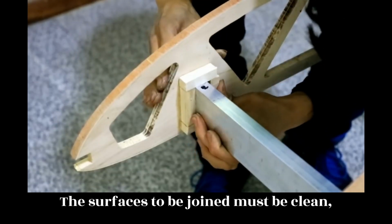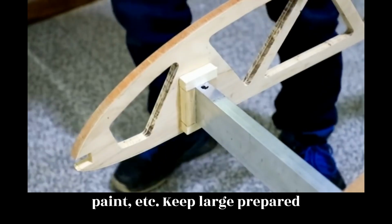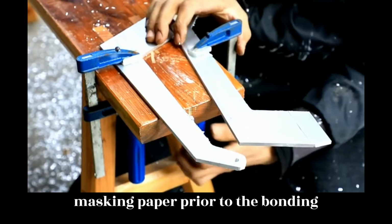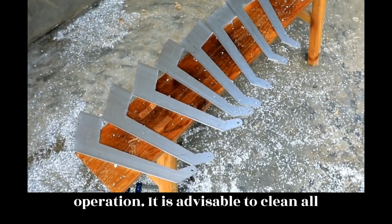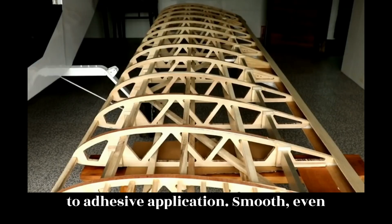The surfaces to be joined must be clean, dry, and free from grease, oil, wax, paint, etc. Keep large prepared surfaces covered with a plastic sheet or masking paper prior to the bonding operation. It is advisable to clean all surfaces with a vacuum cleaner just prior to adhesive application.